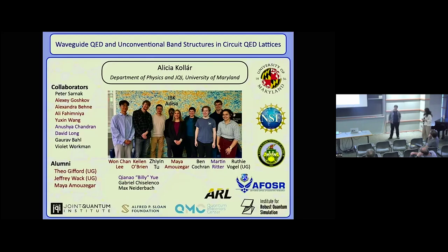The thing that we've actually started to really see is that the tight binding approximation is not good enough. So we have hoppings of about 40 or 80 megahertz and a frequency of 5 to 10 gigahertz. And that's just large enough that we're starting to see terms that were neglected by the tight binding. So some counter-rotating terms and some intraband terms.